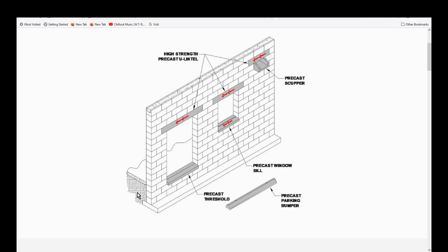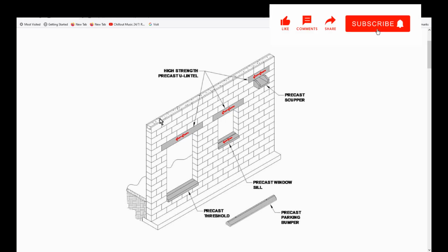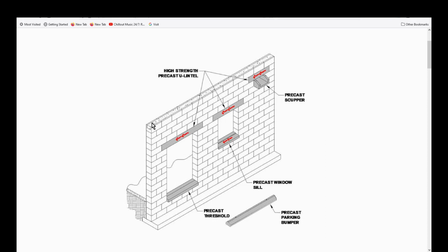And you can see this is all on block course, just like I'm showing on the CAD system. And other things too, you might have a bond beam on top. So there's a couple different ways to do that. So here we got a U block that these cinder block manufacturers make. They call them a lintel block as well, I think, or bond beam block. So that would be a typical top course for that, or they could just power nail on some plywood on each side and make this thing pure solid concrete on top.